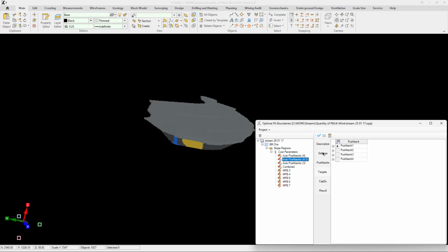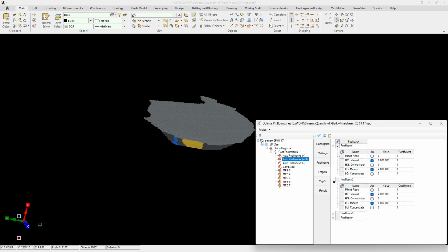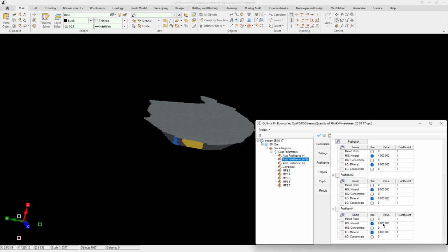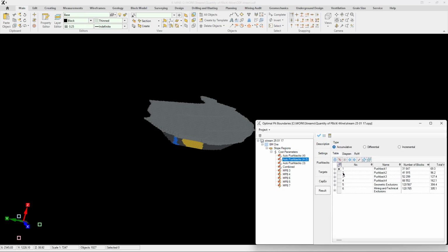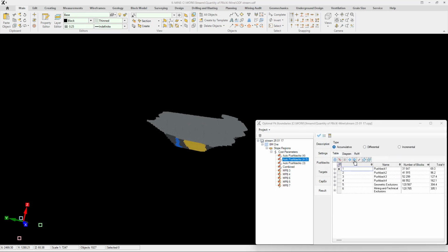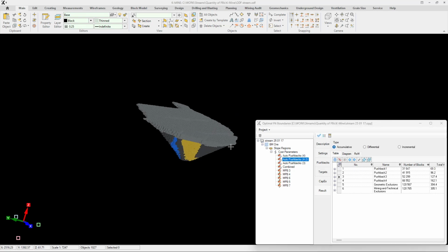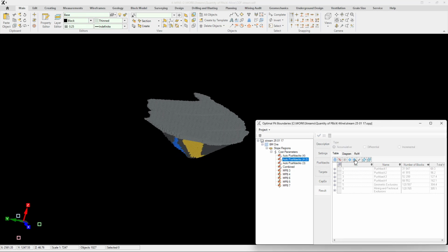This is expected. The algorithm goes through multiple steps, creating areas, checking constraints, validating geometry, and more. But the advantage is that each resulting pushback is guaranteed to be mineable, with a continuous working platform ensured. Another great feature in K-Mine is the ability to duplicate your setup, tweak the parameters, and generate new versions for comparison.